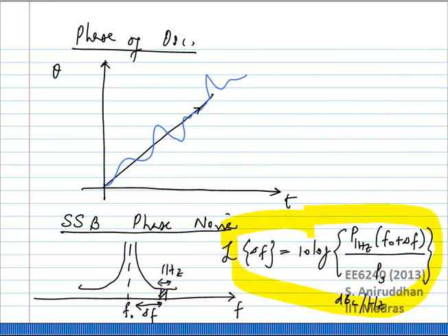And we said this is really noise in the phase of the oscillator, and there is nothing to actually reset the phase of the oscillator once it has changed due to noise, right? So really the phase of a free running oscillator is undefined. There is nothing to control it, and more or less the ideal oscillator should have a constantly increasing phase. But if you take an oscillator with noise, you will get some variation around this due to phase noise.